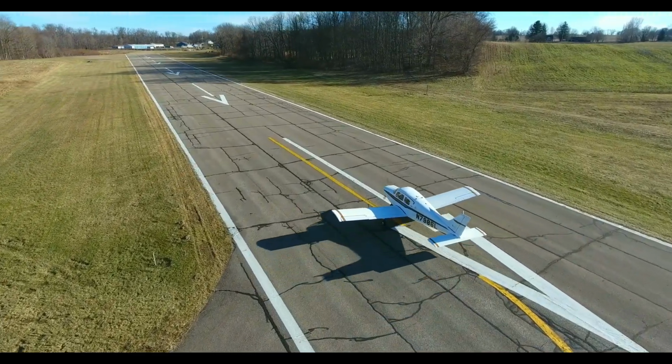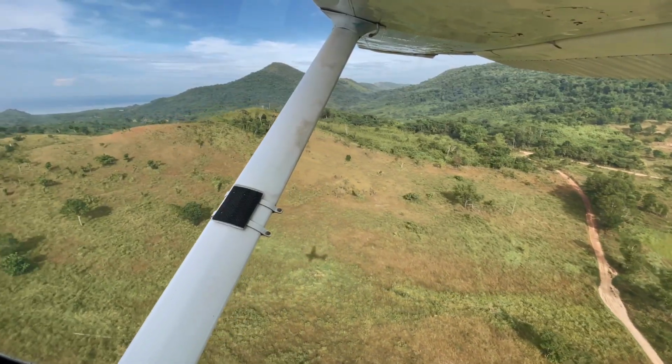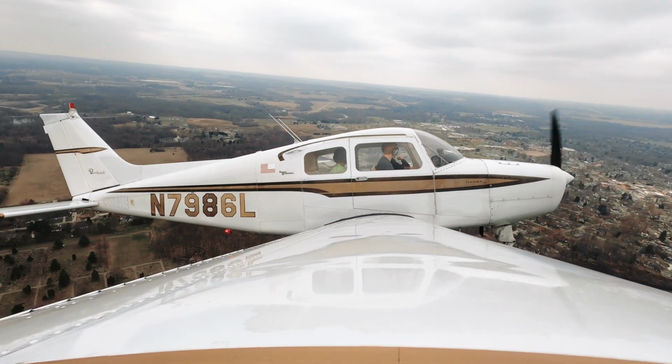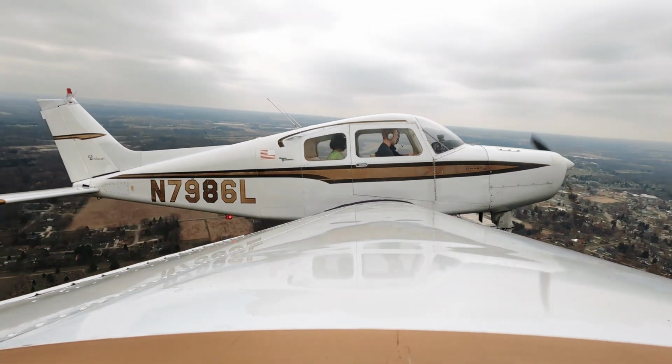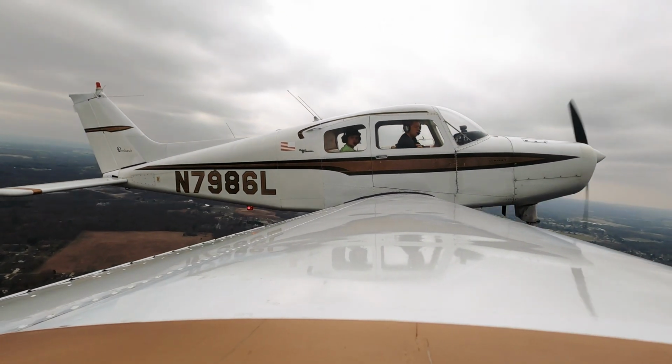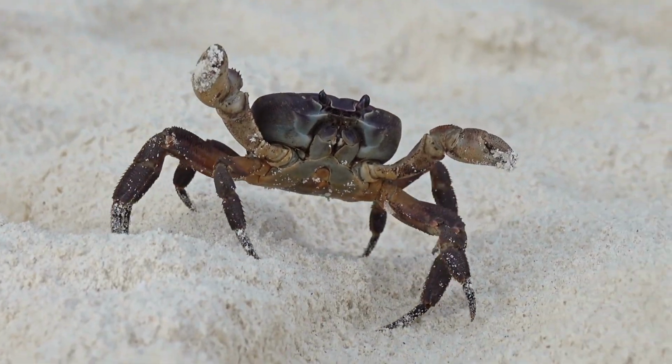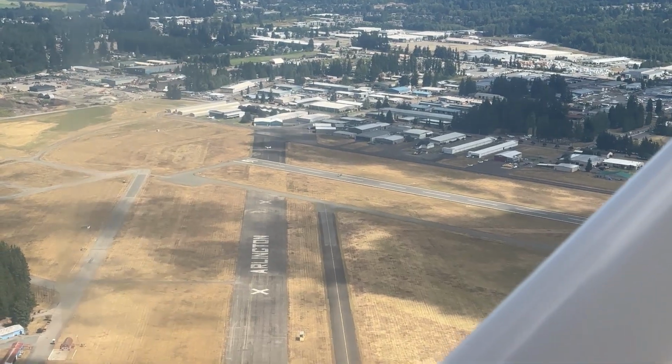If started on the surface, you will climb out to 700 feet above ground level and make a turn to crosswind. You continue climbing to 1,000 feet above ground and make a level turn to the downwind leg, during which you maintain 1,000 feet above the surface while flying parallel to the runway. You may need to crab into the wind to account for any crosswind. Abeam the numbers, you will begin your landing flow.